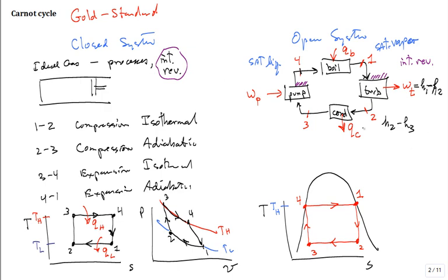Now we'll continue on. What about the work of the pump in terms of the enthalpies? It's going to be h4 minus h3. And the Q of the boiler in terms of enthalpies, h1 minus h4. Okay, make sure you can walk around the system like that.